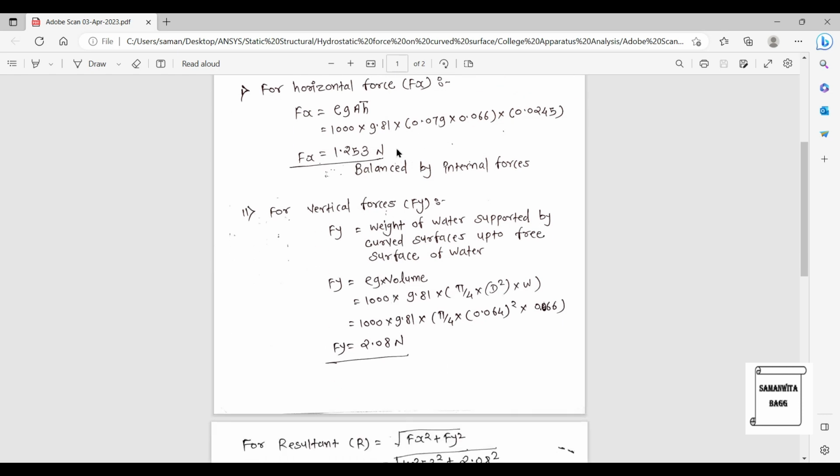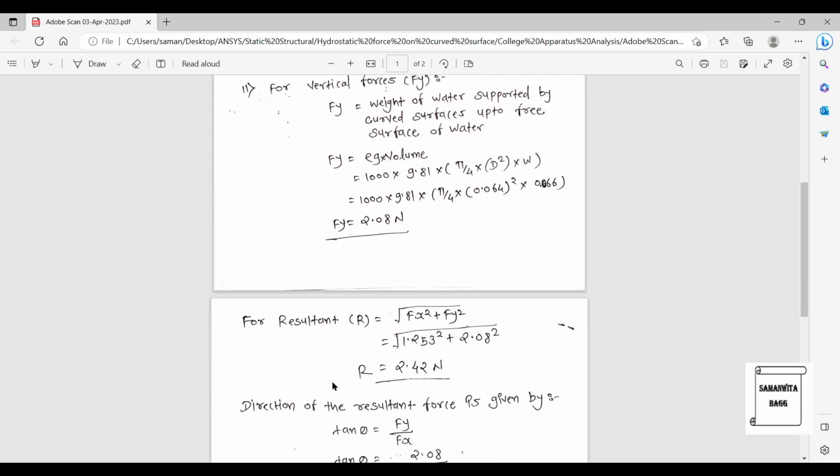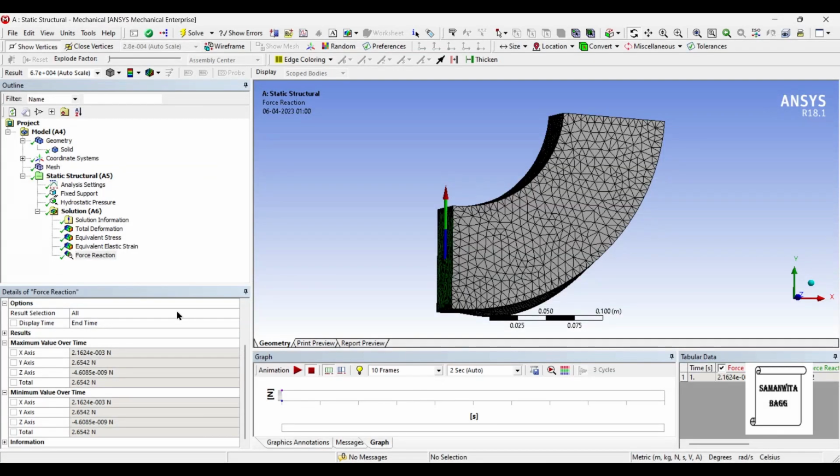So when we solve in this fashion in the class, we generally use two components, and hence these two have to balance out and figure out the value of R for us. But when we use software, there are three directional forces. So whatever force you must have got in the x direction gets somehow balanced with the z direction force. And that's how you can say that this value of x is not wrong. It is just that it is one component of three components here.